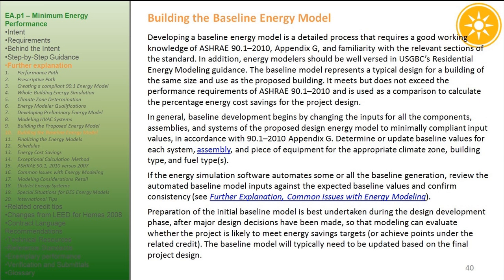Building the baseline energy model. Developing a baseline energy model is a detailed process that requires a good working knowledge of ASHRAE 90.1 2010, Appendix G, and familiarity with the relevant sections of the standard. In addition, energy modelers should be well versed in USGBC's residential energy modeling guidance. The baseline model represents a typical design for a building of the same size and use as the proposed building. It meets but does not exceed the performance requirements of ASHRAE 90.1 2010 and is used as a comparison to calculate the percentage energy cost savings for the project design.